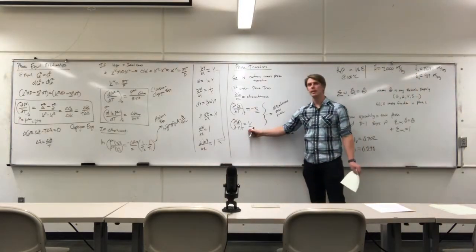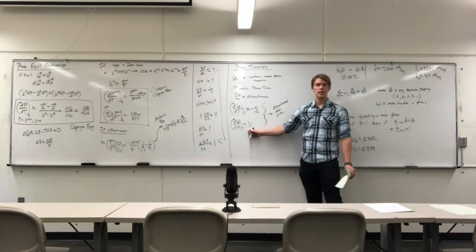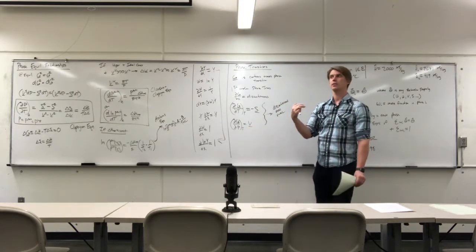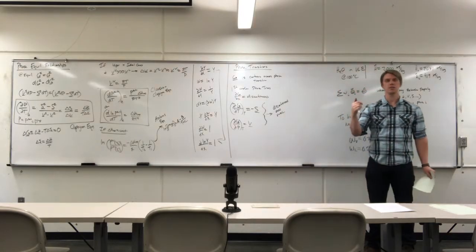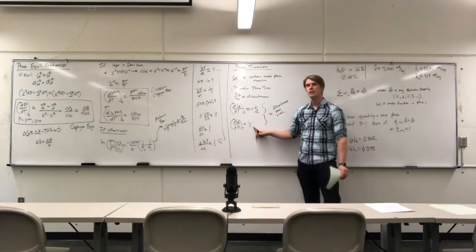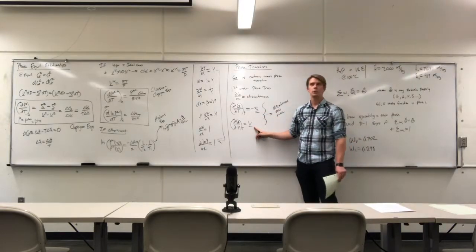The density of a liquid is fully defined based on its temperature and pressure. The density of a gas or a vapor is fully defined as a function of temperature and pressure. When those temperature and pressures happen to meet, that doesn't mean that the specific volume of the liquid and the vapor are the same.